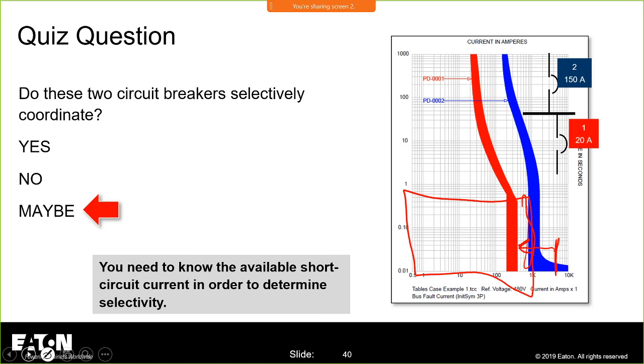Okay. How do I lower fault current? I can tell the electrician to take a couple laps around the building with the conductor before he lands it on that downstream breaker. I could add a 1-to-1 transformer. We saw that yesterday from a short circuit perspective.